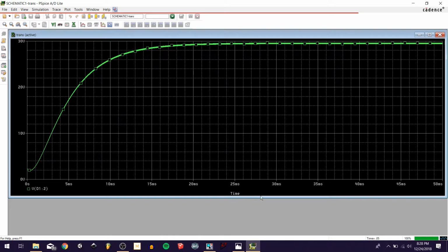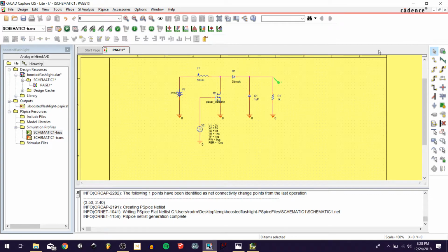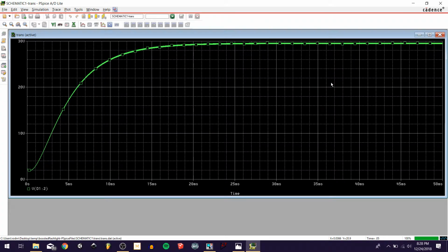You'll notice that the time is the x-axis, and over here on the left it looks like we have voltage. And this is, again, since we set that output marker over here, we wanted to observe the voltage on this node. And this is just like if you're attaching a multimeter to it physically, is what that probe's trying to indicate, which is kind of a cool feature of OrCad. But what we're observing is that node voltage.